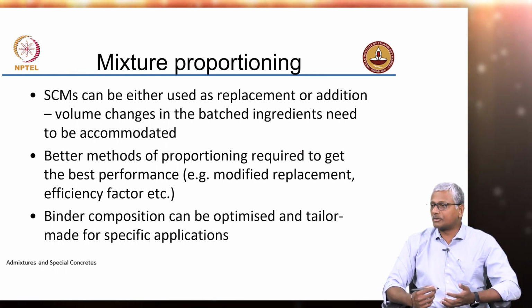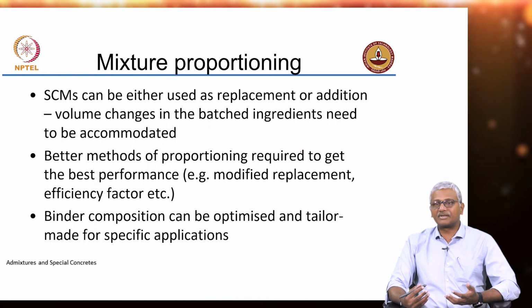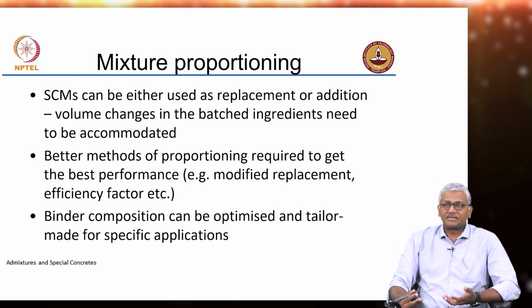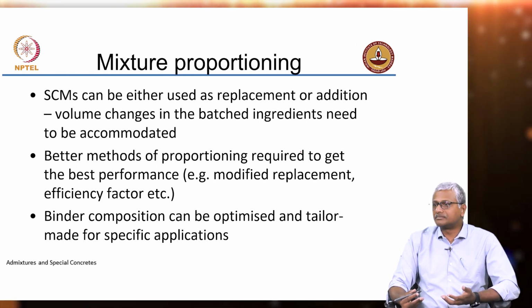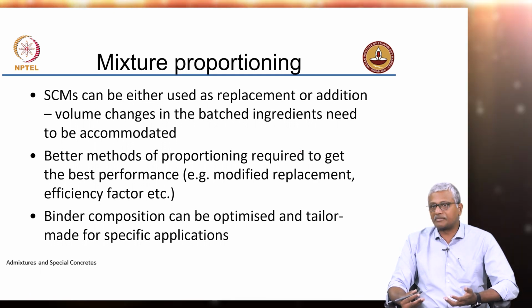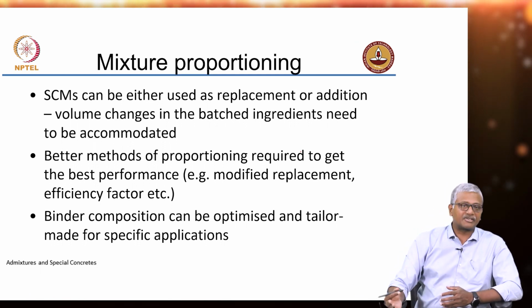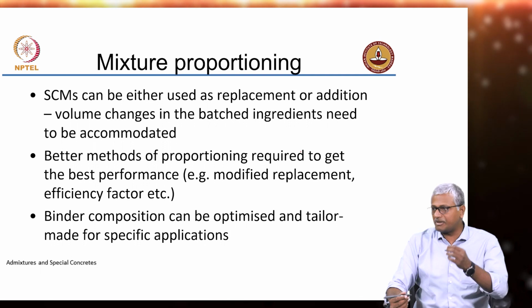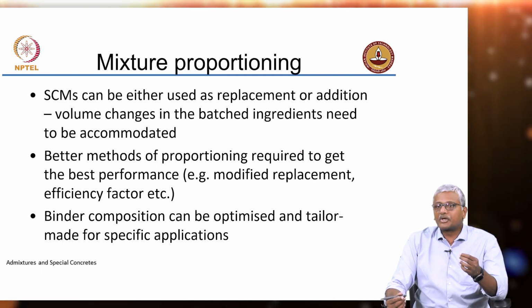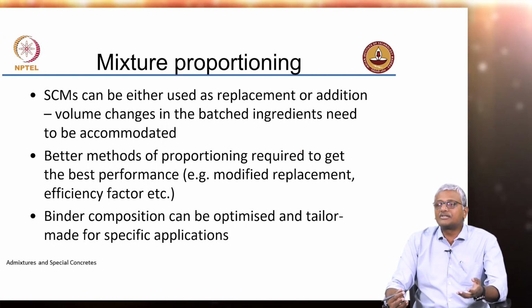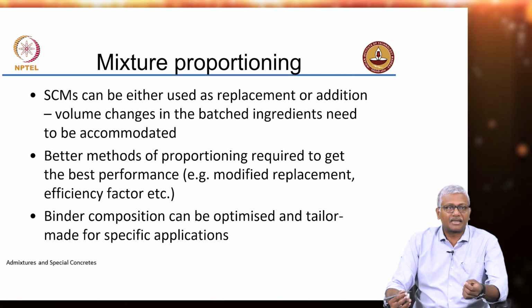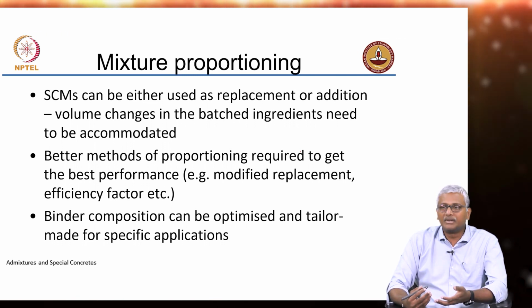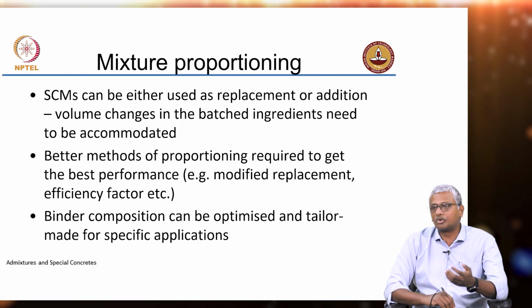They are highly pozzolanic, no? A lot of active silica is available, but is there enough lime available in the system? There is not enough lime available in the system. Of course, there are secondary effects also, because many of these materials are extremely fine, because of which they will increase your water demand significantly.